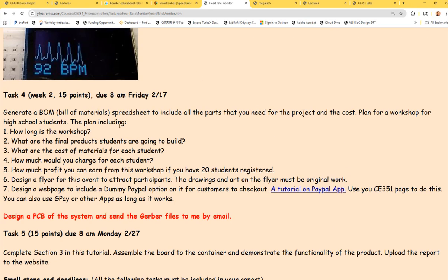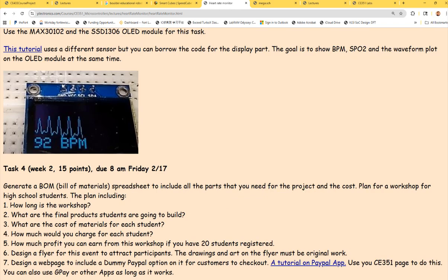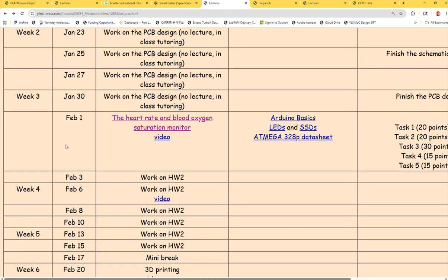And this one could be really simple, because when you are prototyping your design, you could just grab a breadboard, because all these pins are available. These are DIP pins. You can directly plug them into the breadboard and use jumper wires to make the connections, right? Then program and design your code. When that is working, you just put everything on the PCB. It should work on your PCB as well. So that's another resource available for you guys.